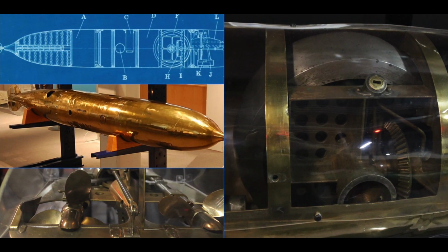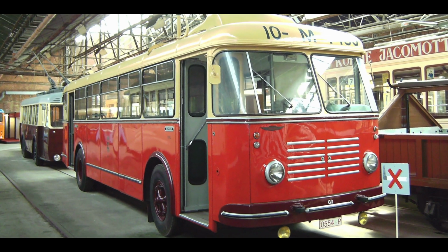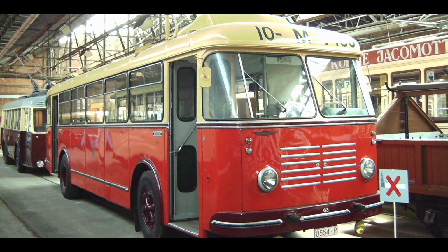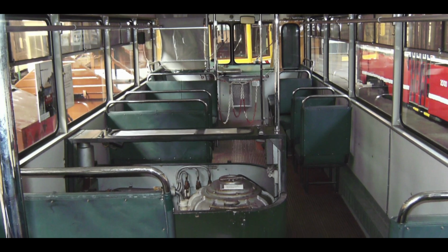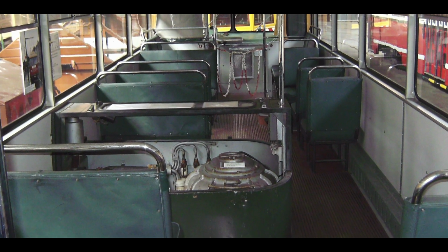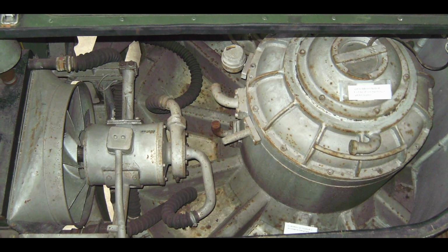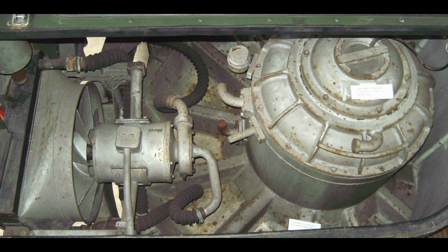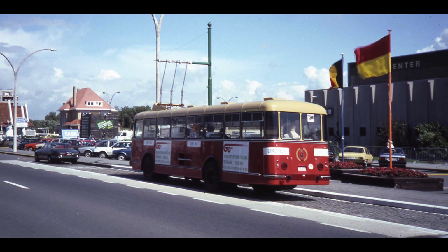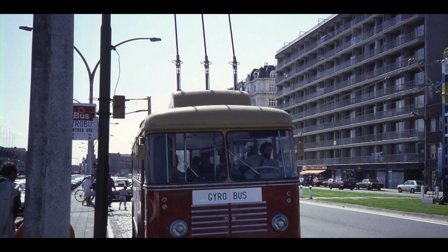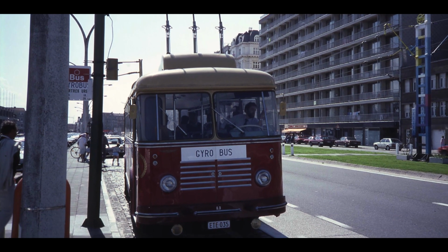provided directional balance. In the 1940s, the concept of flywheels was used for transportation by the Swiss company Oerlikon when it released its carbon-free bus containing a flywheel for energy storage. The gyrobus used energy from the grid to spin up a flywheel system, which operated as a generator while it was on the move. And when the flywheel was completely charged at about 3,000 RPM, the bus could run for about 6 kilometers at speeds up to 50 to 60 kilometers per hour.